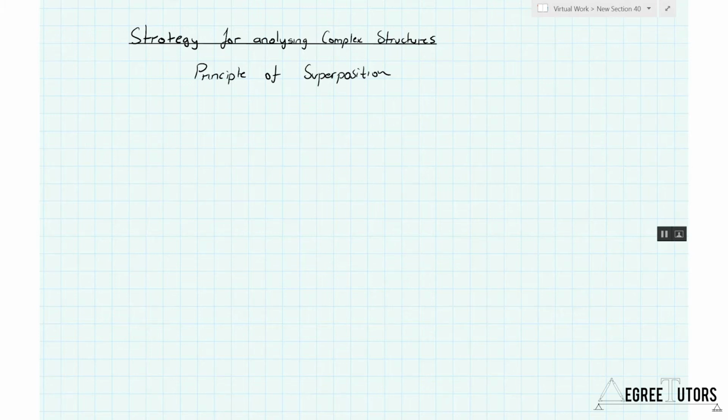So let's think about the simplest type of structure we can come up with. So let's start off with a cantilever. And I'm going to give it some thickness here, just to indicate that that's going to be a member that will experience some bending. Now, so far, that's just a regular structure. To make it a compound structure, we need to add something to it. So if I'm looking at this as an engineer, the obvious thing I want to do is provide some support over to that right-hand side to stop it dipping down. What I'll do is I'll say, let's put some kind of a tie on that right-hand end like so.